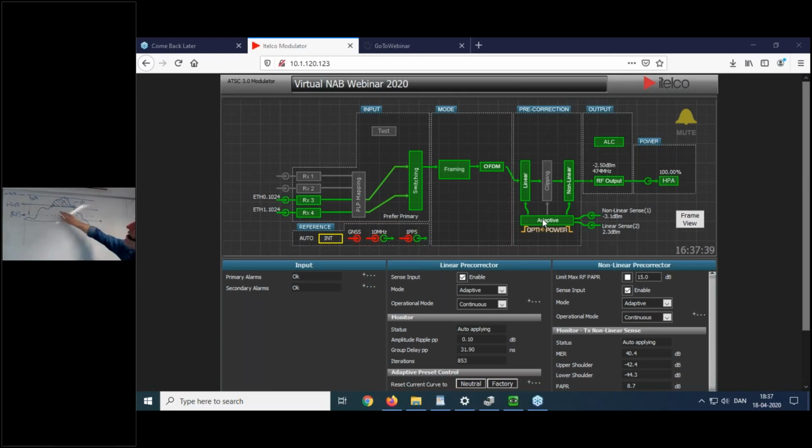So the transistor remembers whether it has been coming from a linear region and going into saturation, or has been in saturation and going into the linear region. That's the strongest mechanism behind the memory effect. Simply to illustrate that: we cannot treat the signal when we do precorrection as if there was no memory effect, because then we would not be able to linearize in this very important region.